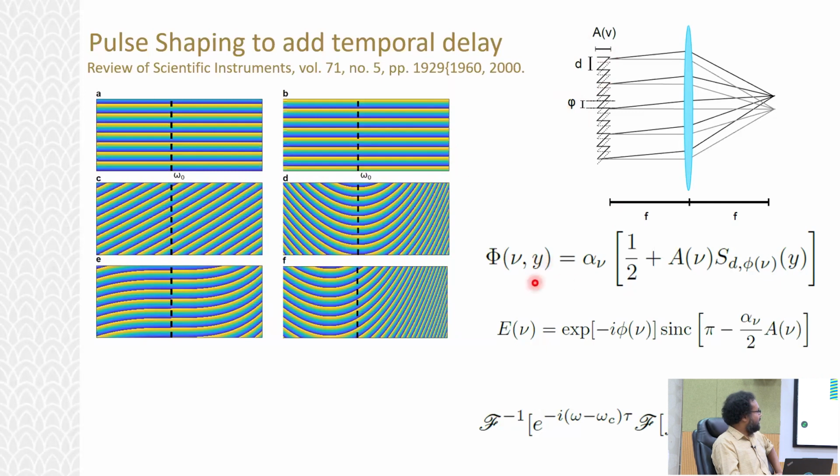Okay, there's the phase applied, and you can show that if I have an input field, some f of t, what I'm getting out is actually f of t plus tau, which comes from this, and that is roughly the phase adder. Now the thing that I want to highlight is that if you go through the math, you will see that there is one carrier frequency coming out.